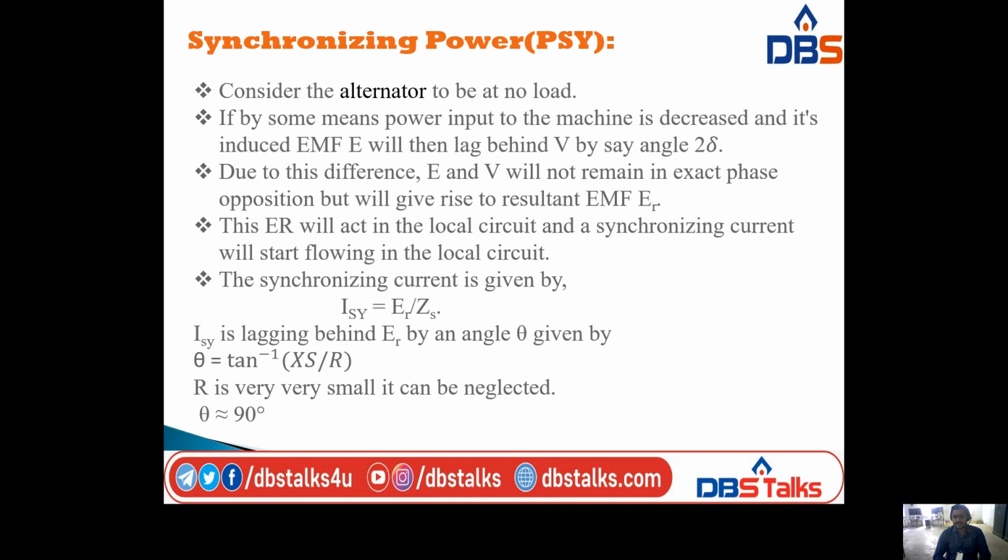This ER will act in the local circuit and a synchronizing current will start flowing in the local circuit. The synchronizing current is given by I suffix Sy equal to Er by Zs, that is, the resultant EMF divided by the synchronous impedance.